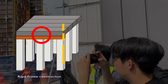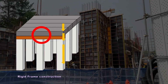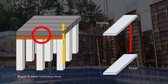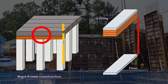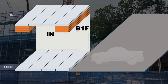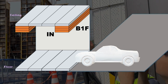The main reason we chose a rigid frame structure instead of a mushroom structure, which is more economical, is because the efficiency of a low floor-to-ceiling height is significantly reduced due to the site characteristics of our project. We designed our apartment to have a deck-type base parking lot that allows for entry from both the outside and the first floor by utilizing the terrain's height difference.